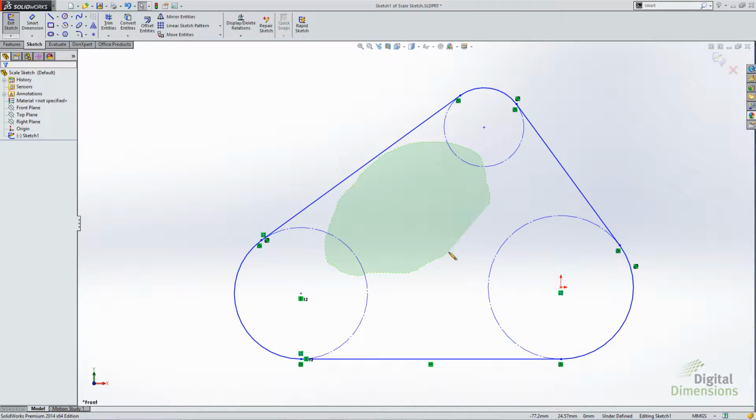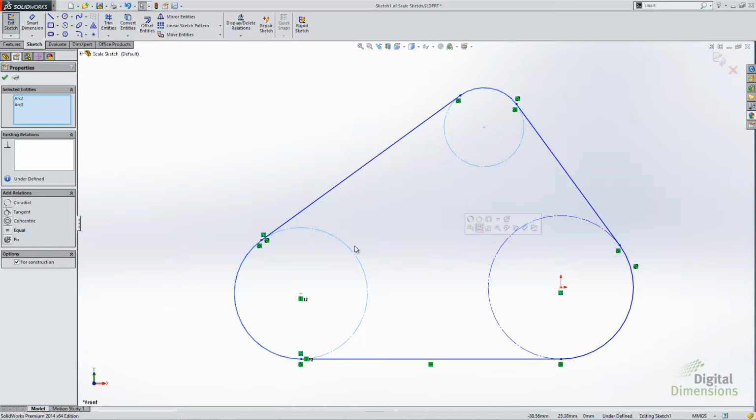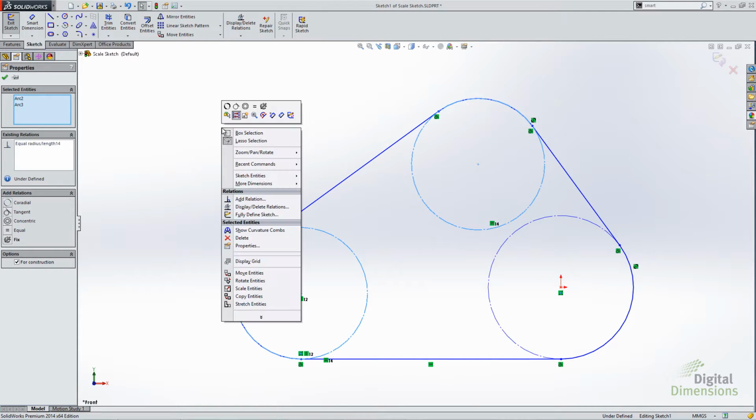And I don't even have to close this. It'll close itself. You can see by the green area. When I let go, only the items I want are selected, and it preserves that cross selection versus the left to right, right to left type selection. So now I can quickly set those things to equal.